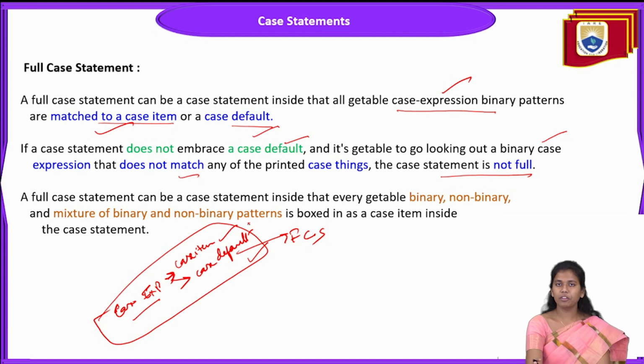When it is not matching either the case default or a case item, we call it a not full case statement. The expression is not matching with respect to the case default statement or the case item statements.